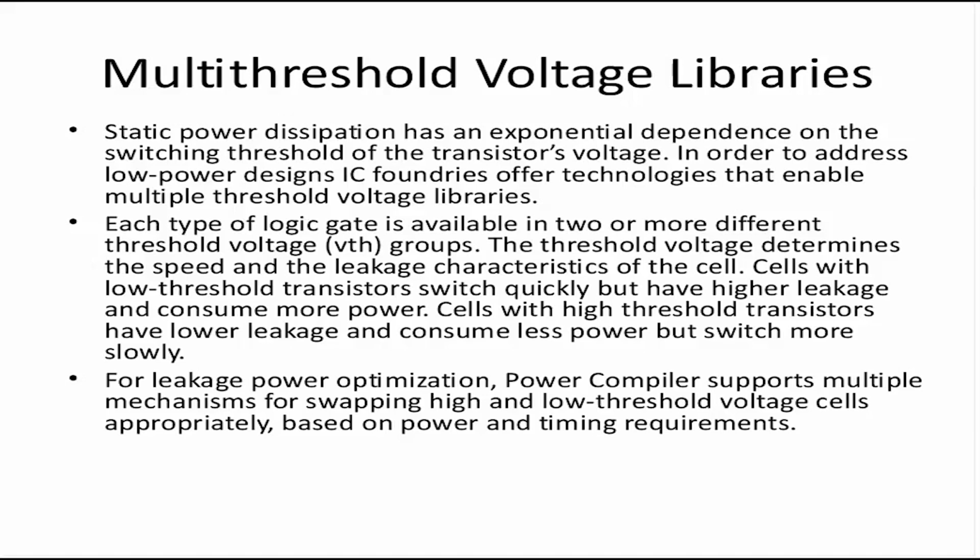They do change. So one methodology I can apply is that I synthesize with high VT, but I enable standard and low VT only after placement and route optimization. What it does to my design is that my design is majorly high VT, and only the real critical paths, which appear after routing, have either standard VT or low VT. What this gives me is a design that is optimized for power and optimized for timing. Right? There are many ways by which you can achieve this.